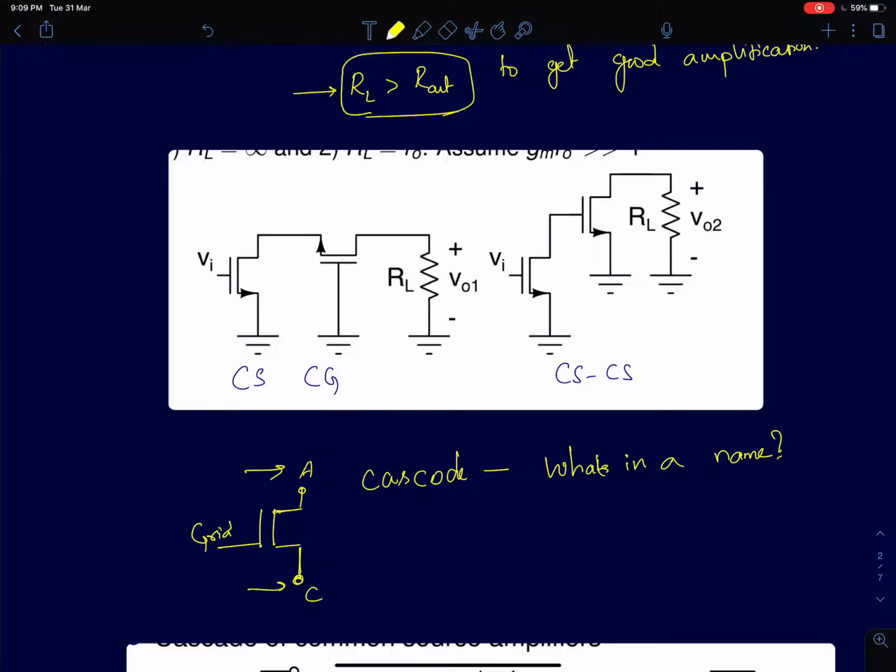If you recall, a vacuum tube essentially has a coil which is heated, and that coil acts as a cathode. So it is nothing but a coil which generates electrons, and we had another plate which was connected to a positive terminal called the anode, and in between there was a terminal called the grid terminal. So this was the model for a vacuum tube amplifier. By controlling voltage on the grid terminal, they could control the flow of electrons between cathode and anode.